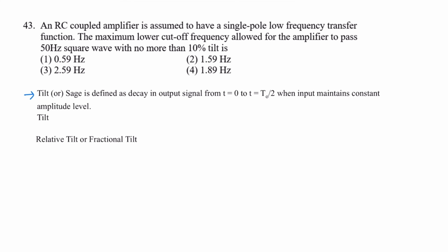So tilt is given as ΔV0 = Vm T0/2RC. So the fractional tilt is ΔV0/Vm = T0/2RC.